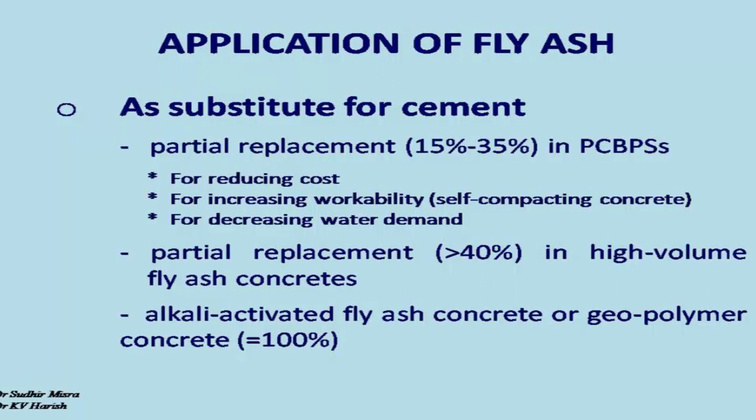Yes, definitely it will affect, but alternatively what we also do is use activators such as sodium hydroxide and sodium silicate in extremely high quantities, and that will react using a process called geopolymerization. The hydration of the geopolymer system is totally different from the Portland cement based paste system. Typically you do not have calcium silicate hydrate gel or tobermorite gel getting formed as the strength giving phase in Portland cement based paste system. The same will not be formed in the geopolymer system.